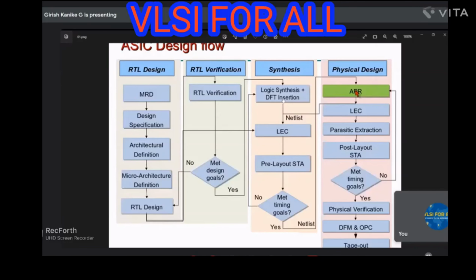If there is any optimization chance where a gate needs to be connected in another way, or replaced with another gate, for example an AND gate replaced with a NAND gate plus an inverter to make the same logic with some time duration variation, such alterations will be done in the logical synthesis, and then again the netlist will come out. The same process repeats until the timing goal is met. Once the timing goal is met, we'll get the same netlist, the GLN.